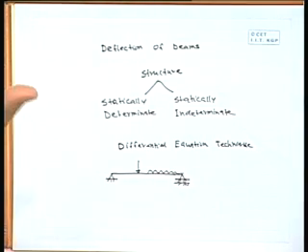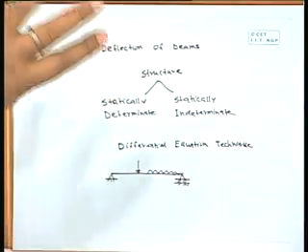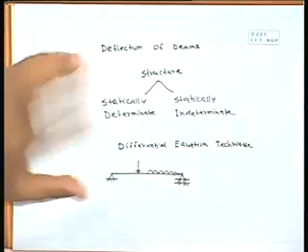At least 3 directions should be restrained. It should not move this way or that way, and it should not rotate. So, all possible movements we have to restrain. These are the minimum, and if we go beyond the minimum, then it will be statically indeterminate.